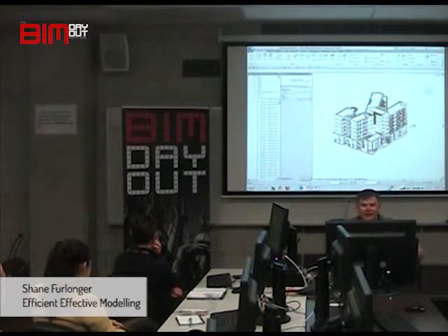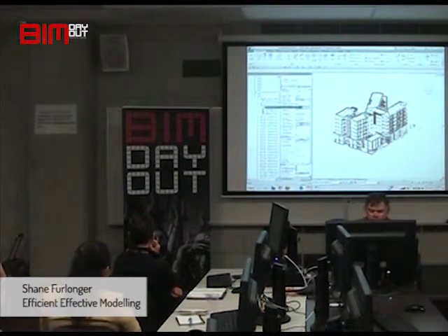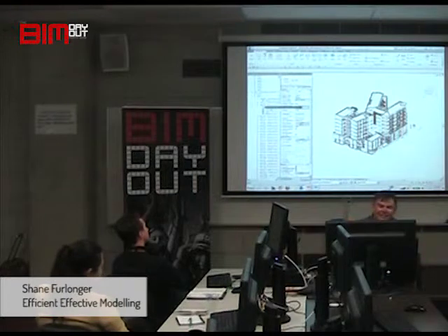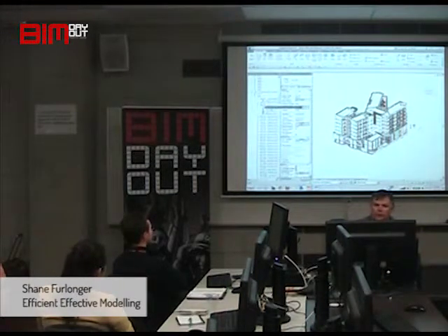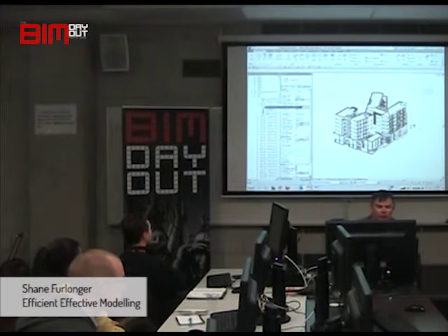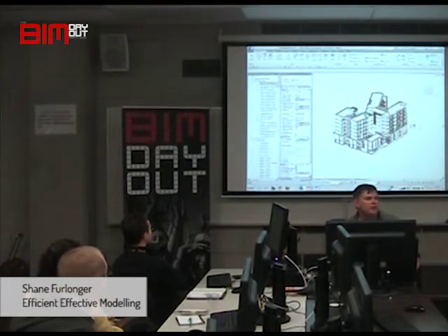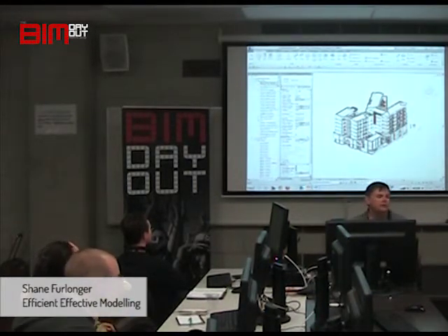Those views are annotation views. So whatever's in here, I call an annotation view. Oops, that's not what I did when we started, that's just a schedule. Whatever's in here, floor plan, whatever's in there is an annotation view. So all you do on that view is you annotate. You dimension, you tag, and you note. You don't model in it, because there's things turned off that you don't know are turned off when you're going around changing your model.